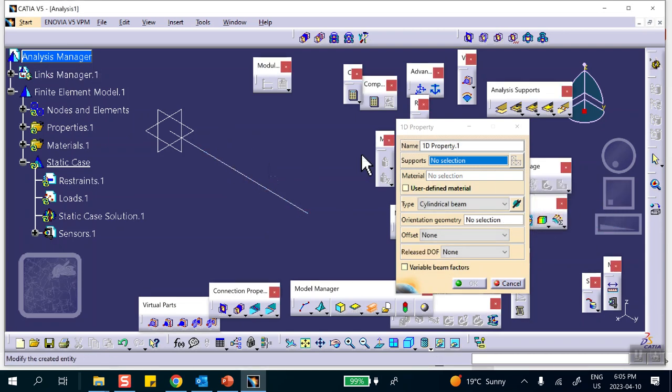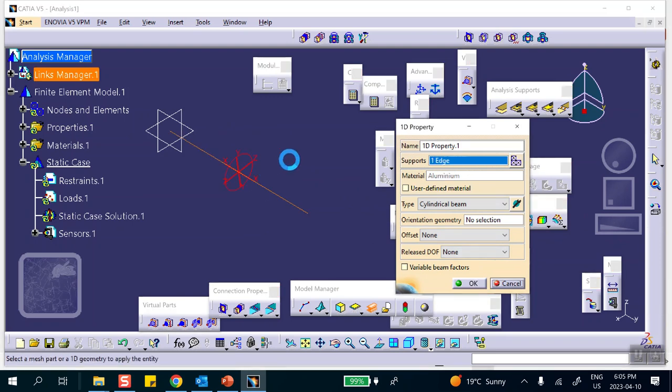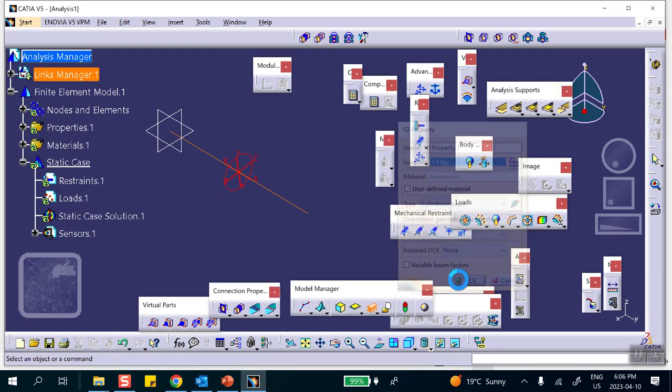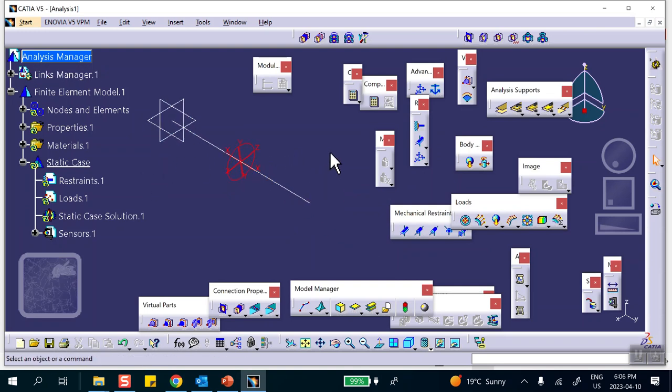And I'm going to select, these are totally irrelevant. The Young's modulus of the aluminum, the density of the aluminum, the cross-section here that you can see, these are totally irrelevant to the calculation. They should not influence. This definitely will not. But that Young's modulus and density also, you have to put a small number so it won't. Now, if this is bothering you, you can always hide it, or you can make the radius smaller, but it doesn't bother me, so just close it. Because it's cylindrical, you don't need an orientation point, and that takes care of it.